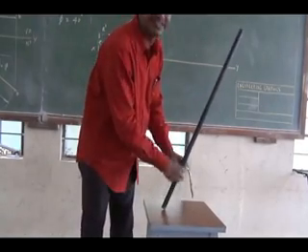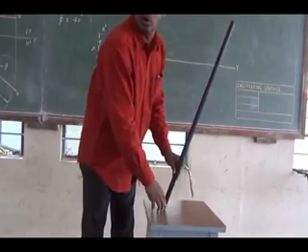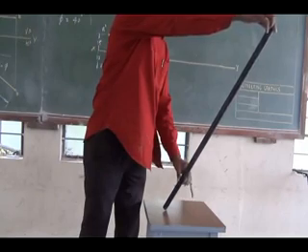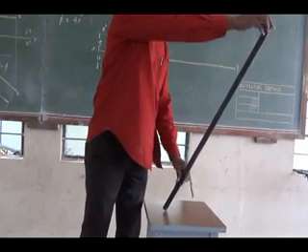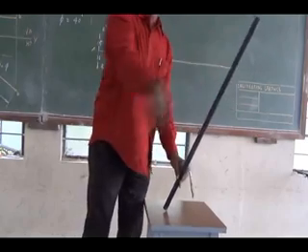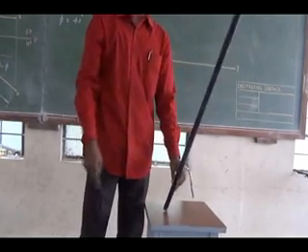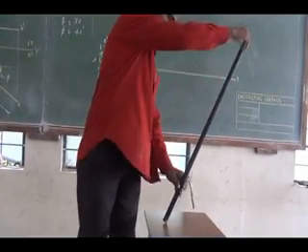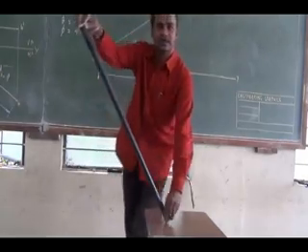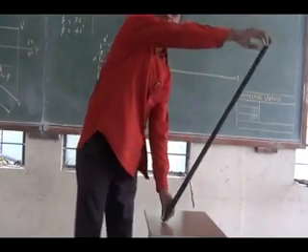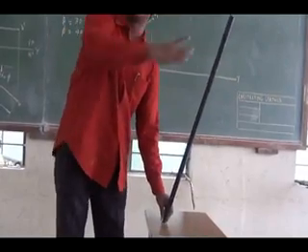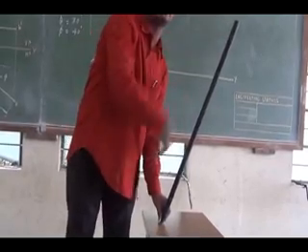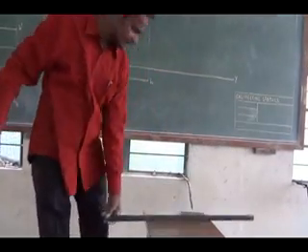So without varying this 30 degree inclination, I am going to tilt this line to VP also, 40 degrees. What will happen to my top view? Do you have any variation in the top view length? This end is going to rotate like a cone. So whatever inclination I tilt, the top view length of this line will be the same. That is the result I will have.